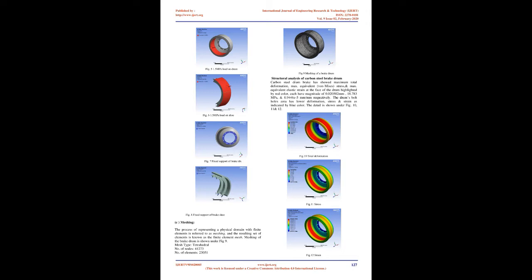To get more accurate temperature distributions they determined the convection coefficient, h, value by analytical or experimental prediction and incorporated it into the model. They checked the design by comparing the maximum stress obtained in analysis against the standard allowable stress value. They found that the design was safe and the brake drum functioned properly under the given load conditions.